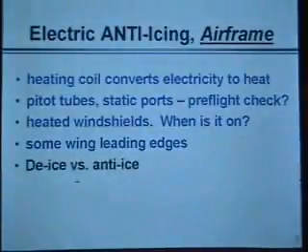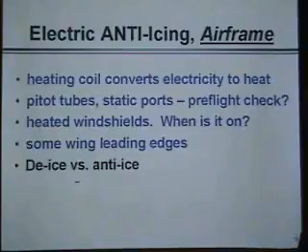So although in all cases here, electric anti-icing for the airframe is designed as an anti-icing system, they will de-ice if the ice forms first, and then you turn it on. Although in all these cases, you're going to want to turn it on prior to the ice forming, if at all possible. In particular, if turning it on would cause ice to go into the engine.